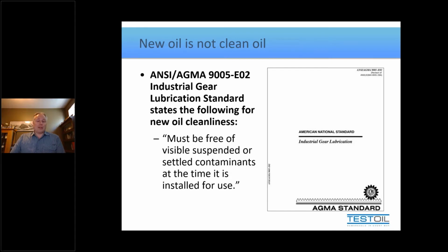If this is the acceptance criteria for new oil delivery, right? Take a sample, look at it in a clear vessel. If you can't see anything in it, good to go. That's not a very good standard. That's a bare minimum, and it's a very low bar to consider. Now, one of the other standards that exists has a bit more to say about this, but still is not really any better, and in fact could be construed to be worse.